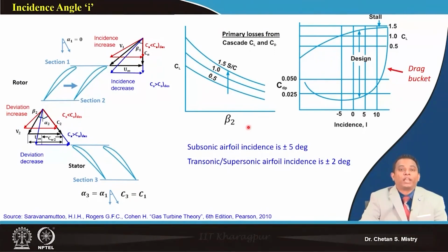Here we need to realize one thing, as we have discussed: the kinds of aerofoil we are using for subsonic application and the kind we are using for transonic application all have different leading edge thickness. So if we consider subsonic aerofoils, my leading edge thickness is slightly higher.